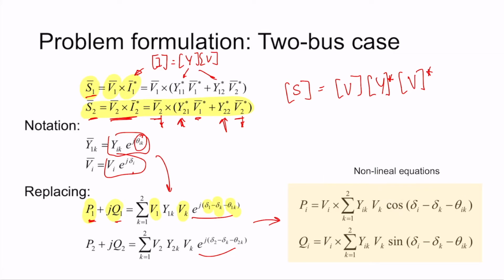If I give you this matrix, of course the matrix comes with the phase angle, and then I give you voltages, you are able to compute for a large number of elements the active power and reactive power which is injected at each node. Simple. Well, another observation, this is a nonlinear equation. And typically we don't know voltages, but we probably know information about the injection power. We can know the demand of one node or the generation at each particular node.